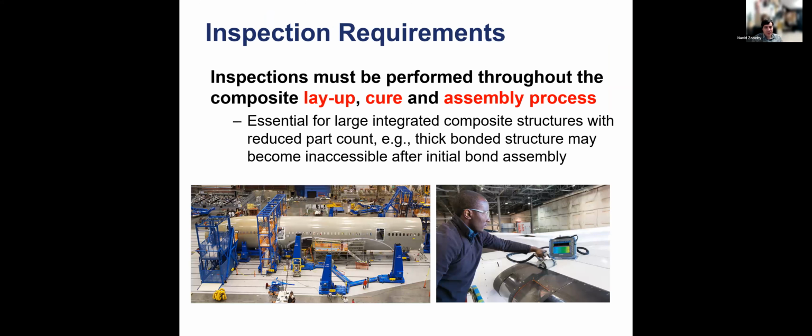Finally, it's not just the layup and cure and assembly, all of those things. At the end of the day, you have to have information on how to inspect this, and if you have bonded joints, what the details of those are and how to inspect them. Ultrasonic inspection, for example, could be part of this process spec or could be a different document. Some of the testing that you have to do after the manufacturing is done, for example, we're going to do these 5 types of tests to show that the final properties are satisfying our requirements, could also be identified inside the process spec.